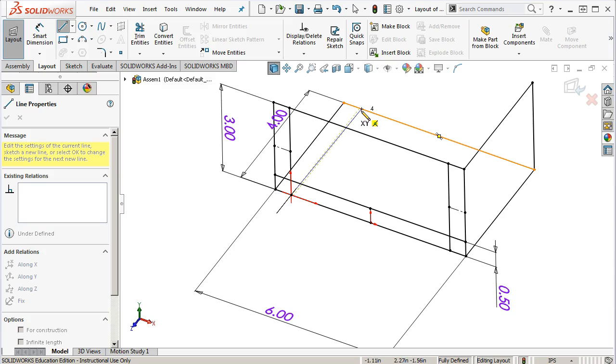So again, I'm not really paying attention. I haven't done 3D sketches in a while. But notice that my rectangle is up and over, and that my origin is doing the XY plane as opposed to tab going into YZ or tab going into XZ. Now when I draw, the box is laying back, and that's kind of your visual reference. You'll pick up that clue, but only after you've made the mistake about 6 times.